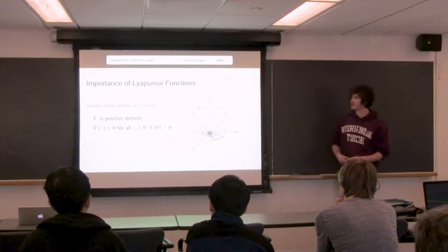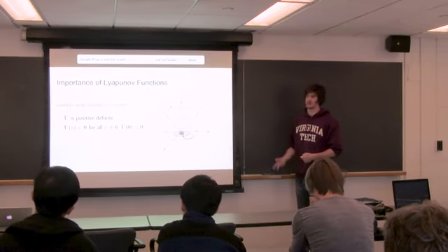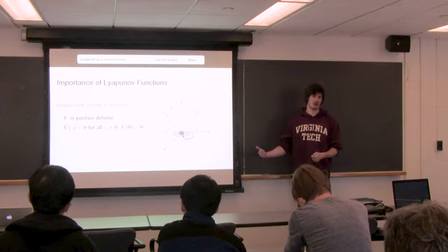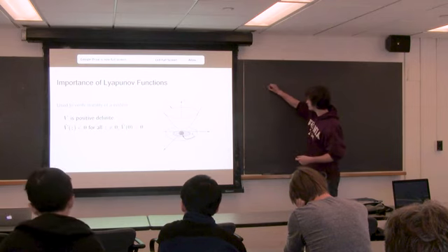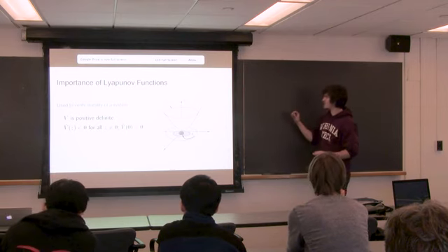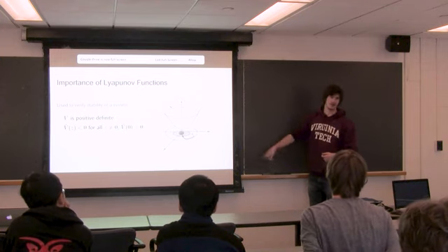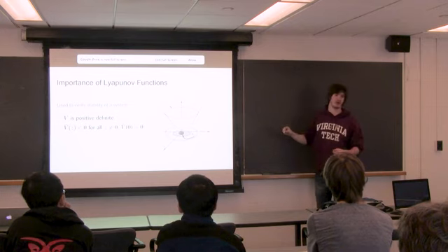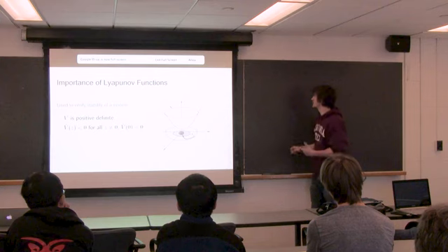But in nonlinear systems, there's global exponential stability, there's asymptotic stability, and there's stability in the sense of Lyapunov, which is what we care about. Say this is your nominal, and globally exponentially stable means that no matter where you start, anywhere on the board, you're going to converge back to this equilibrium point at an exponential rate. That's the best case scenario, that's what you want.